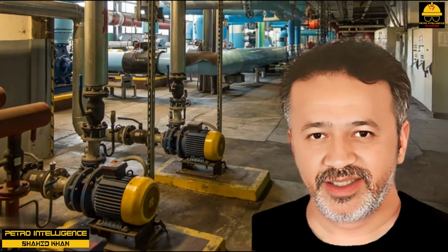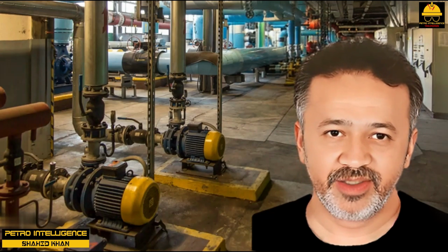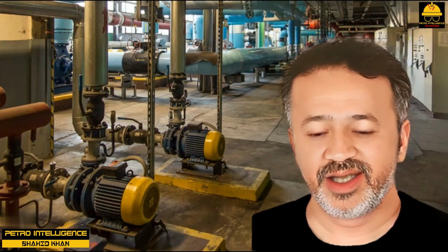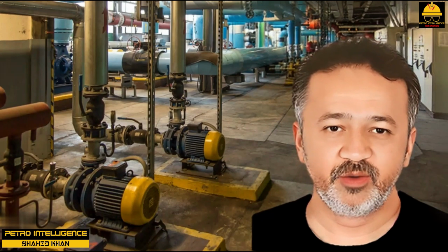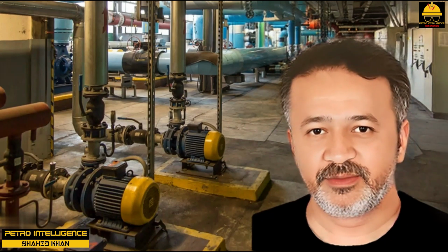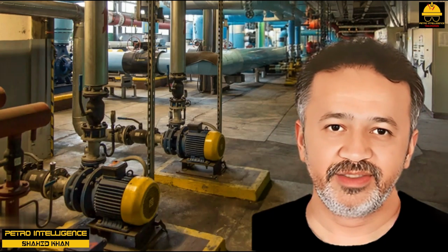Finally, the steam turbine's buckets can foul with hardness deposits from the steam. This reduces the turbine efficiency and may prevent a pump from running at its rated speed. Injecting steam condensate into the steam supply can remove such deposits.